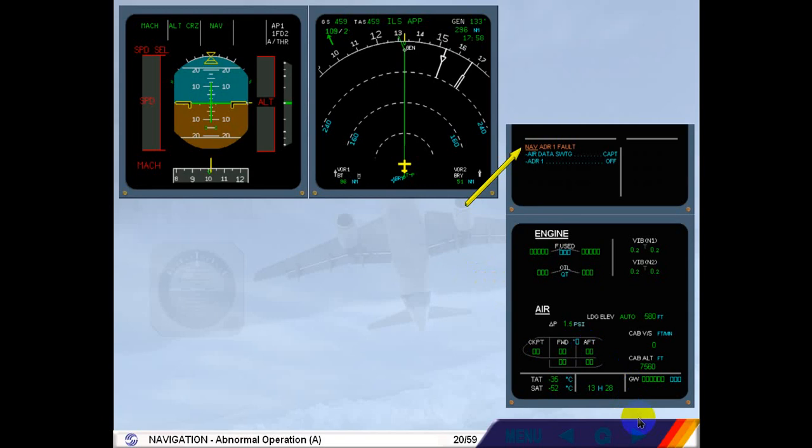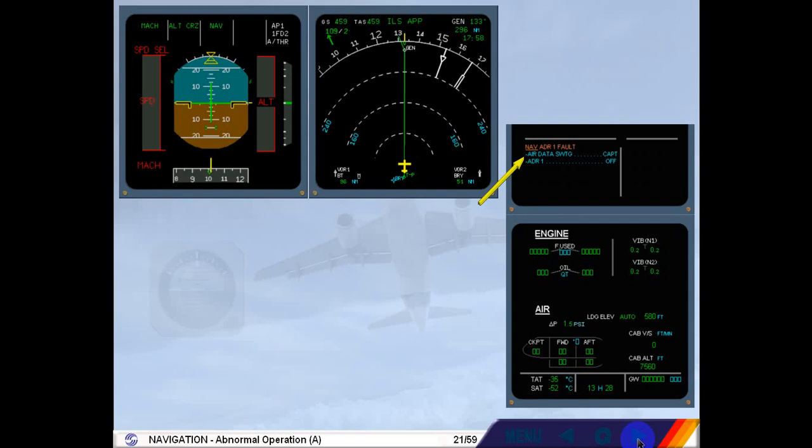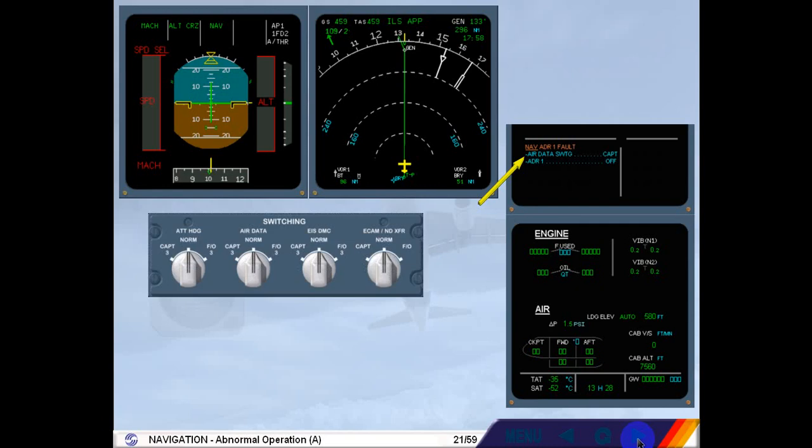Notice on the PFD, the speed, altitude, Mach and barometric indications are lost. The procedure requests you to switch the air data switch to the captain position.